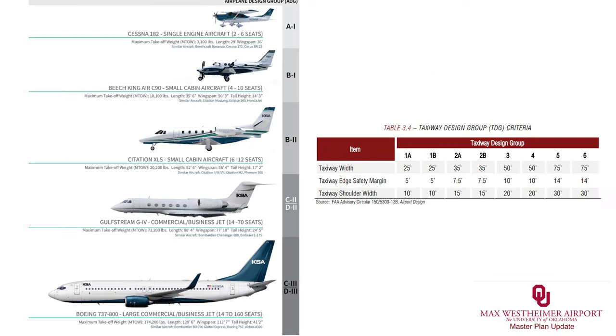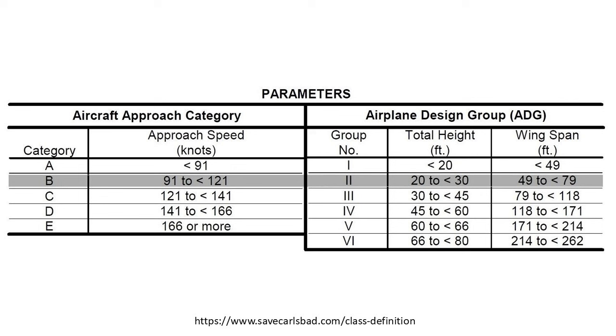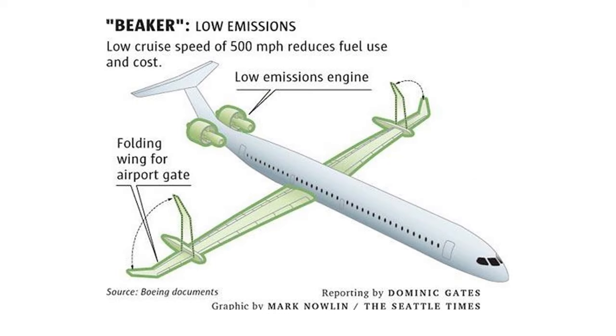Often, aircraft will have wingspan limitations to fit into certain areas in an airport, such as specific taxiways or into specific terminals. There's also a thing called an aircraft design group in which different aircraft pay different amounts in airports depending on how large they are, and bumping up into larger groups increases costs everywhere. A winglet has the advantage of not increasing wingspan, but increasing the effective aspect ratio by increasing the effective wingspan. A creative solution to this is the hinged rake winglet, which folds up upon landing to prevent commercial aircraft from bumping up into higher and more expensive design groups.